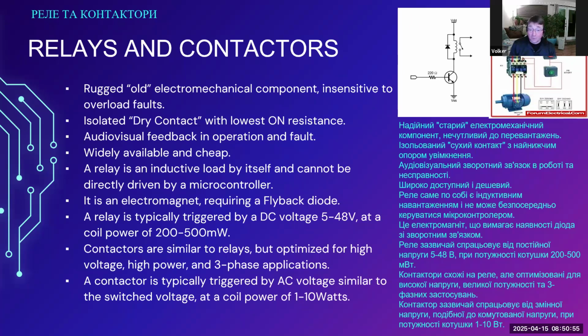For example, if you're switching an inductive load with a relay and you forgot the flyback diode to protect the relay contact from the high voltages that an inductor can generate, you will see a spark across the contact, if the relay package is transparent.